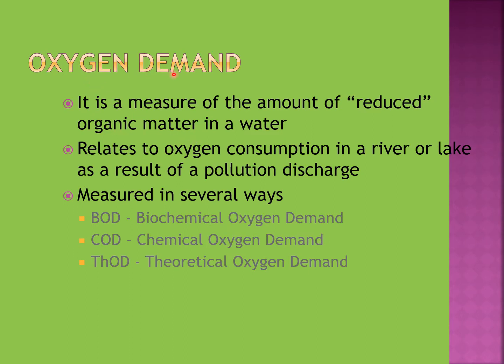Oxygen demand is the amount of oxygen required to oxidize the organic matter present in a wastewater sample. So we can say it is a measure of the amount of reduced organic matter in water. It relates to oxygen consumption in a river or lake as a result of a pollution discharge. As you know, oxygen consumption depends on discharge of pollution. It can be measured in several ways, such as biochemical oxygen demand, BOD, chemical oxygen demand, COD, and theoretical oxygen demand, ThOD.